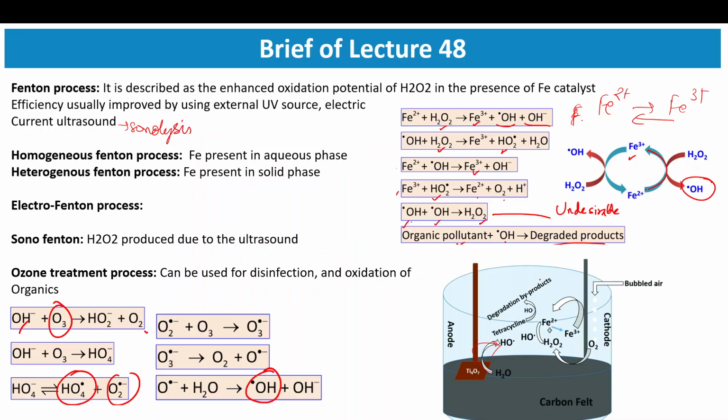Next is ozonolysis or ozone treatment process. Now, ozone can have multiple applications in terms of wastewater. It can be used for disinfection or oxidation of organics, because ozone has very high oxidation potential, and it reacts with the microbes to make them inactive in water, right? So if they are made inactive, the chances of further reproduction and growth of microbes reduce, and hence it causes